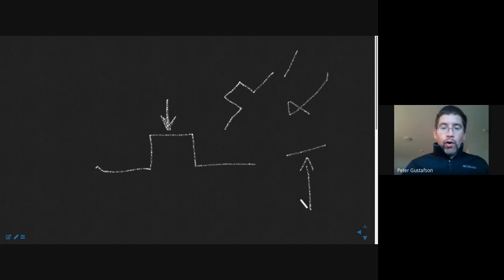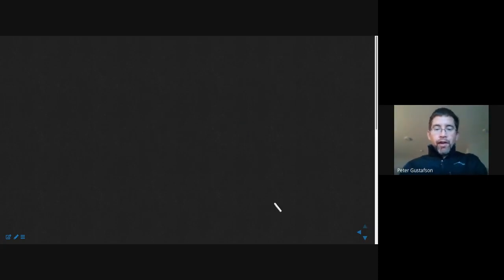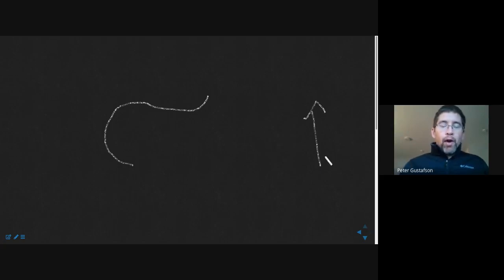Okay, so the intuitive description of this is for any section, and it doesn't really matter what the section looks like, there is a point somewhere in this plane where if I load through that point, there would be no twisting. If I load off that point, there will be twisting. The point is called the shear center.